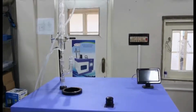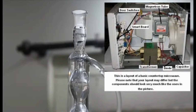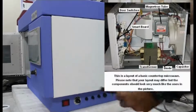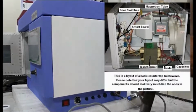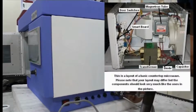For the summary, place the sample in the tube and set the tube on a turntable inside the MAE cavity. When you press the start button, the triac flips to the on position, which starts the electrical current flowing through the microwave. The high voltage transformer begins amplifying that electricity. The magnetron then takes the magnified electricity and converts it into microwave energy. The microwaves are directed into extraction through the waveguide.